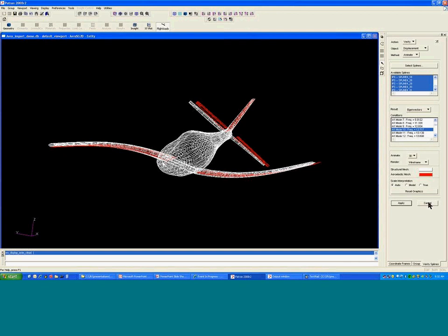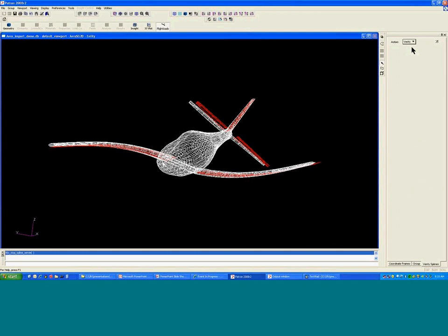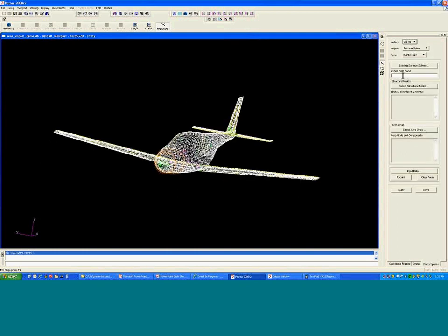Okay, so that's the interactive spline verification, and where this is used is that there is an art to creating splines and figuring out how many nodes you want to connect to, how much you want to connect to grids that are outside your various aero panels, and how much smearing you want to do between panels. And so what's nice about this is, as you go and create a particular spline,